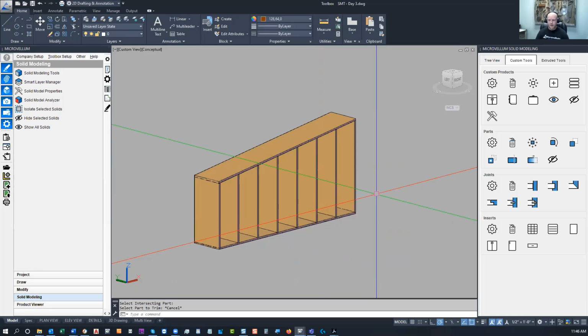You're going to spend a lot more time using things like press, pull, or subtract to get this product to taper from one end to another. Take advantage of the whole spectrum of the tools that are available to you. This got us most of the way there, right?